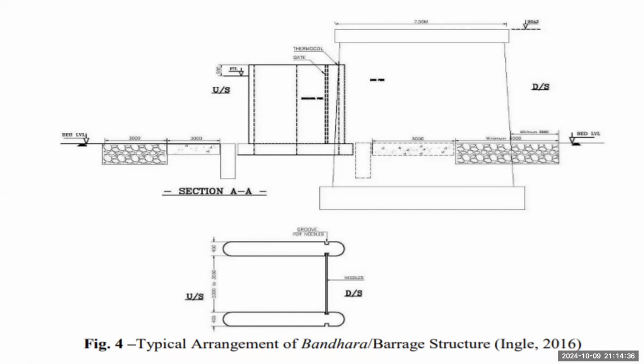So in Bandhara irrigation system, water overflows over the Bandhara, so there is no roadway above the Bandhara. Okay, which is possible in case of KT Weir. So in this figure, we can see the roadway, then the supporting structure, then the piers along with the grooves, and in the cross section, we can see the needle placed in the groove. So this is expected in the answer on the KT Weir. Okay, cross section and the side view, both are expected in the answer on the KT Weir.